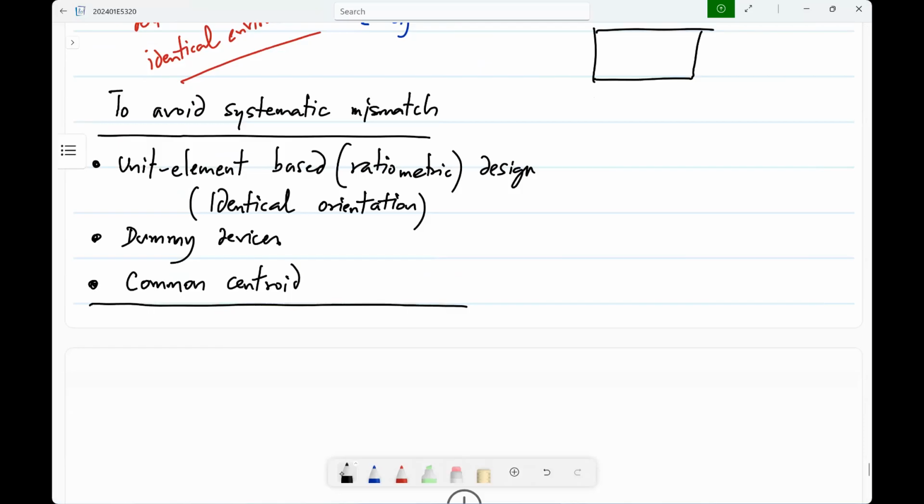Now, the reason I also said common centroid, you have to connect something here with something there, and it can make something complicated. You have to keep in mind that anytime you have a crossover of connections, it's easy to draw wires like this when I'm drawing the circuit. Whenever you have something like this, you will always have asymmetry, because you will make connections on different metal layers.